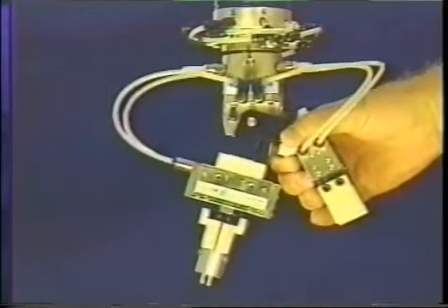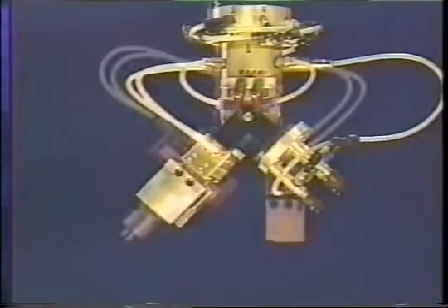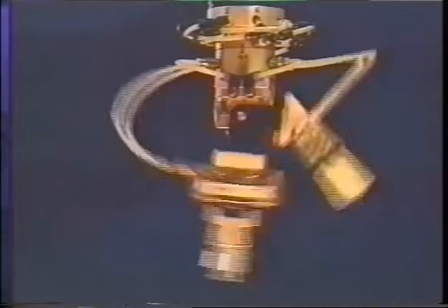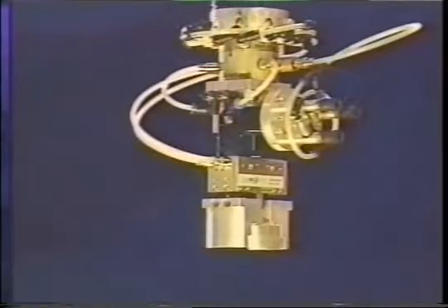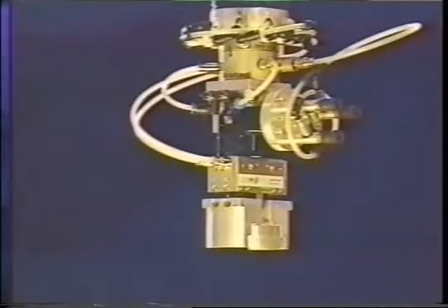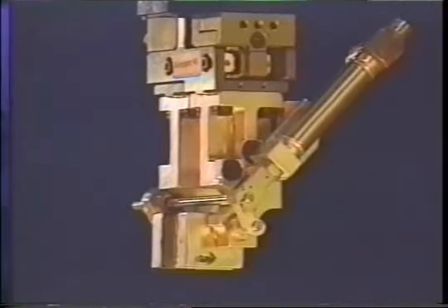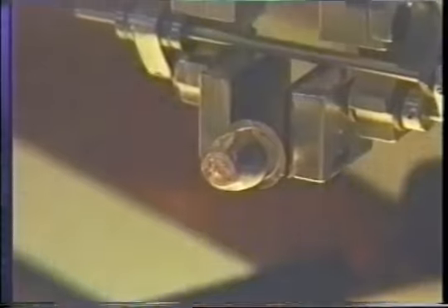In order to grasp a wide variety of objects, a set of quick tool changers and modular grippers are used. Multiple grippers are typically mounted onto rotary wrists, thus reducing the number of tool change operations needed. Since parts must sometimes be fed in orientations that are unsuitable for assembly, a light rotary jaw gripper has been developed. This allows parts to be rotated into more desirable assembly orientations.